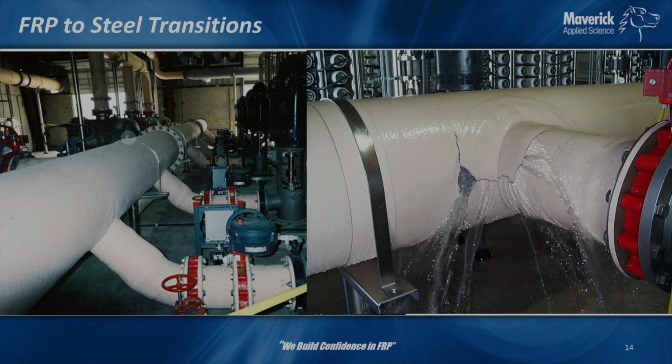Here's an example. This is a big heat exchanger, and this is a cooling water system inside a power plant. What we learned here is we've got this 24-inch line that's tying into the top of this heat exchanger, which I think was something around 50 or 60 foot long. Under normal operating conditions, the power plant is usually running around 160 to 180 degrees Fahrenheit. It's taking the hot water off and trying to bring it back down, coming back out. But we found that this heat exchanger was actually expanding and contracting as well.